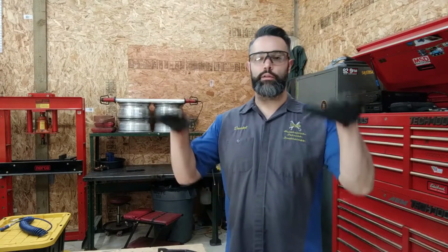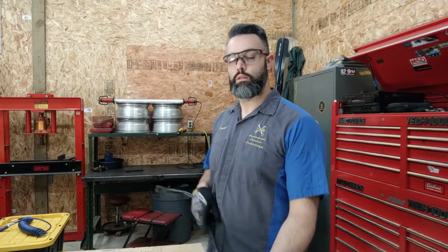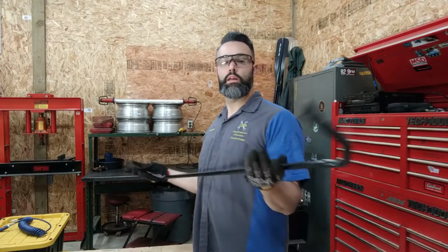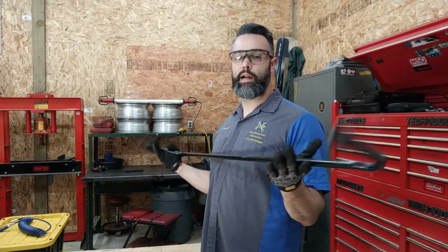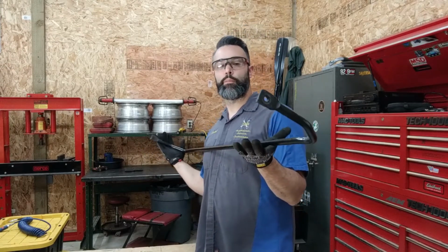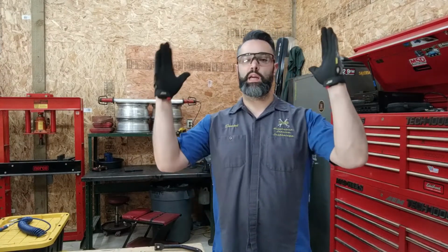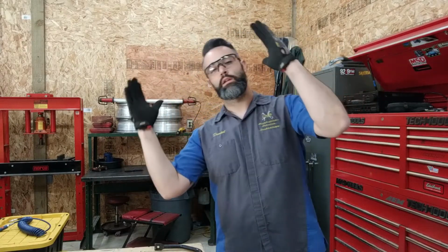When the vehicle is rounding a corner or is on unstable ground and the body wants to tip one way or the other, the job of the sway bar is to resist that movement and keep the tires in more contact with the ground or optimal contact with the ground for better handling and vehicle stability purposes. If the sway bar is not present on a suspension system and the body is trying to lean during an